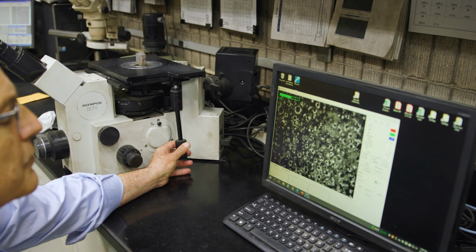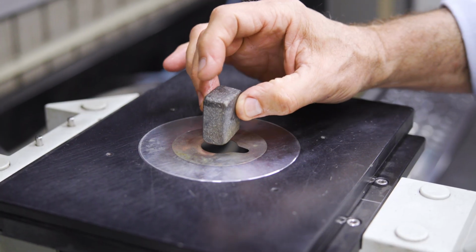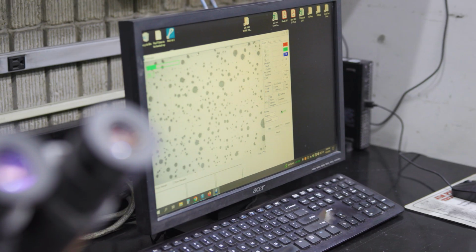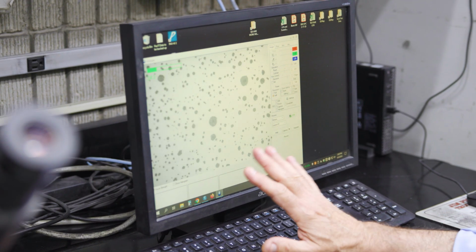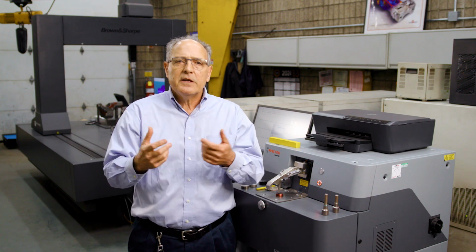The atoms are arranged in a certain way. They have a certain size. Some are bigger, some are smaller. And that carbon is small, it sits in between the iron atoms. The silicon goes there and fights for that same space and pushes that carbon out. So the carbon now needs its own space and is going to meet with another carbon and create graphite.